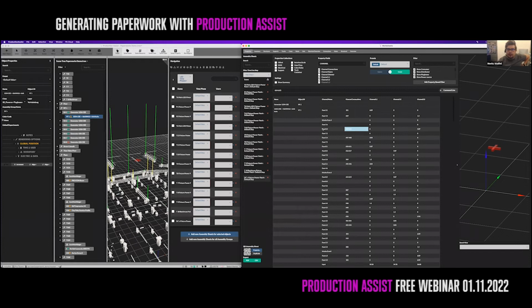I also can enable the specific phase usage of this. So for each of the outputs for the fuses, I see how much current is running through it and to which phase they are assigned. So I see the fuse 8.3 is assigned to the channel 3, so to L3, and approximately uses 5.87 amperes in power consumption in here. That is a really easy way of generating your paperwork.